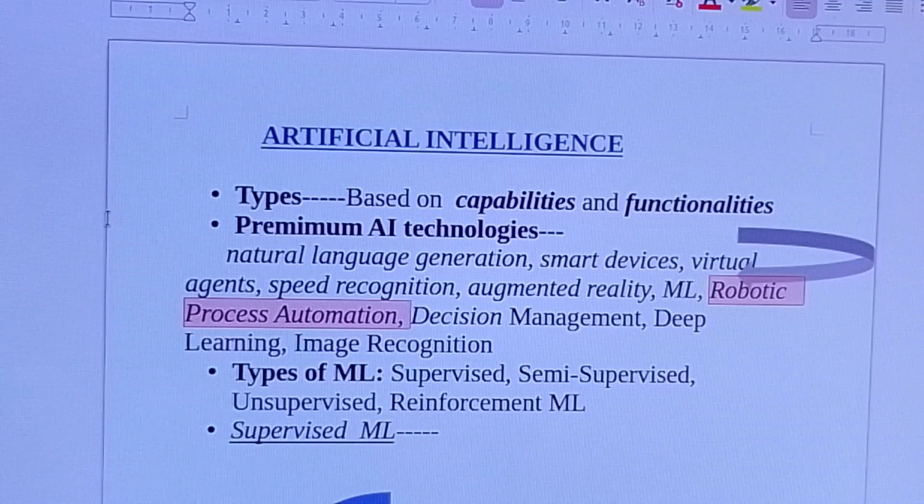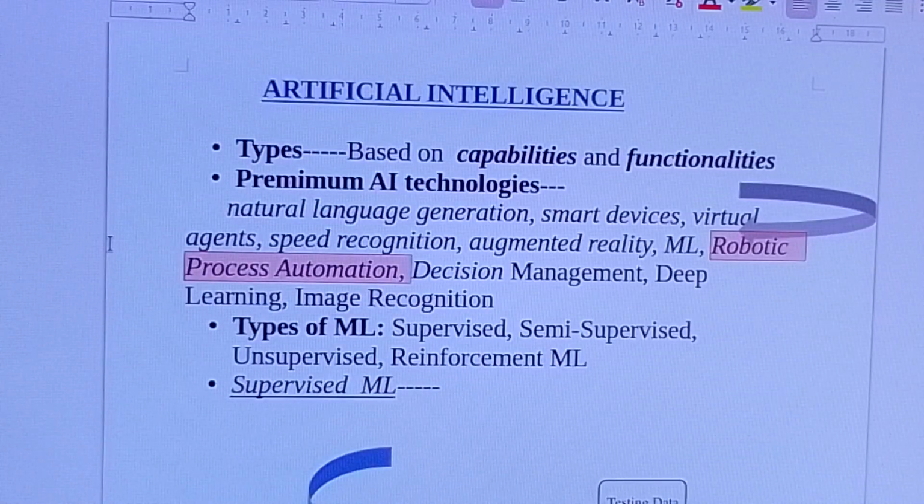The objects should not be pressed hard, deformed, or slipped. Sometimes it's necessary to have prior knowledge regarding the form of the object before it's gripped. Therefore, it's needed to sense and measure all the important geometrical parameters of the object lying in an environment. Sensory feedback is, of course, more important for an unstructured environment, right? That is, an unleveled or unstructured environment.